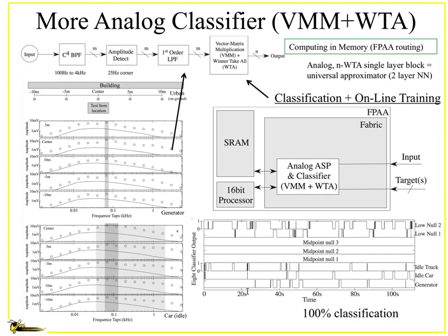And so you can actually talk about classification, and this is a little more in-depth on what one of them would look like. This was an acoustic classifier problem designed to be fairly low power, in the microwatt kind of ranges. You can do a full classification from one end to the other. We took a data set that was developed by DARPA, made it about 10 times harder, and ended up getting basically perfect classification, and we were able to do all the training and learning on the chip, which is very relevant for in-field training, changing, programming, or just programming it in a particular way.